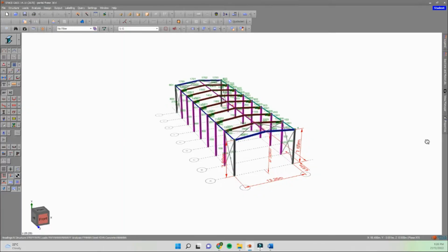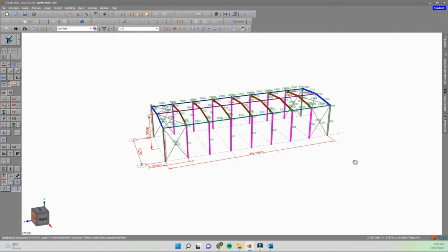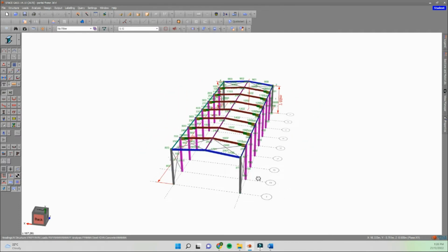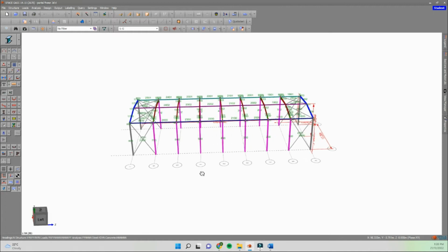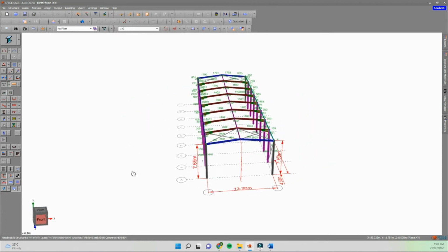After constructing our model in Revit, we were then tasked to translate the design into a 3D Space Gas model whilst maintaining the same parameters. We utilised a structure wizard portal frame builder to construct the base portal frame with relevant length, width, base size, spans and pitch. The relevant haunches and members then had to be included in this model.